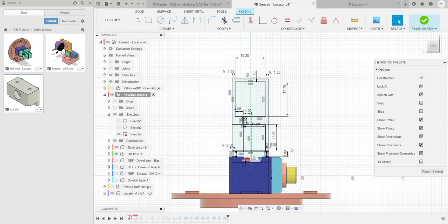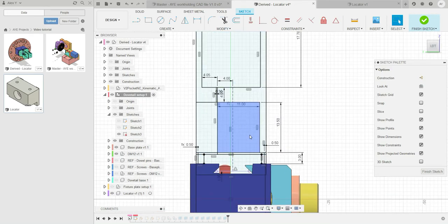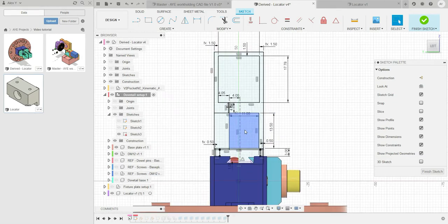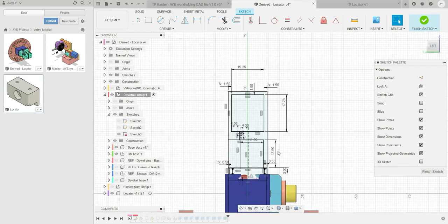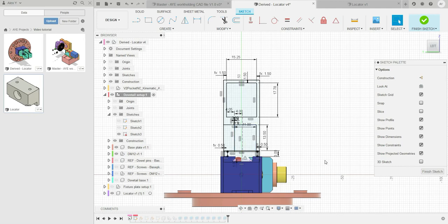As I actually started out trying to locate the part as low as possible, meaning I used as small a piece of stock as possible, but I was spending ages having to think about how to get my spindle to clear and using different tool paths to try and make sure there wasn't a collision. And to save a few pennies on stock, it didn't make sense. Obviously, if you're producing hundreds or thousands of these parts, it would make sense, but most people using the Pocket NC aren't using it for that. They're just doing one-off prototypes and so on. So for that purpose, just use extra stock. It just makes life easier.